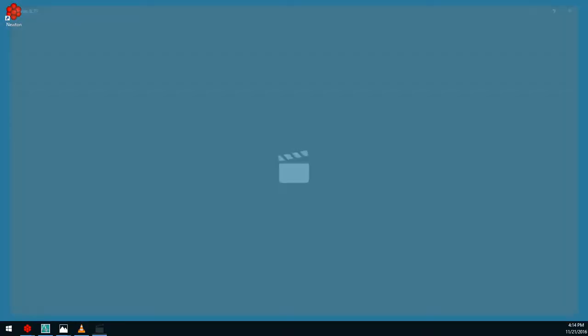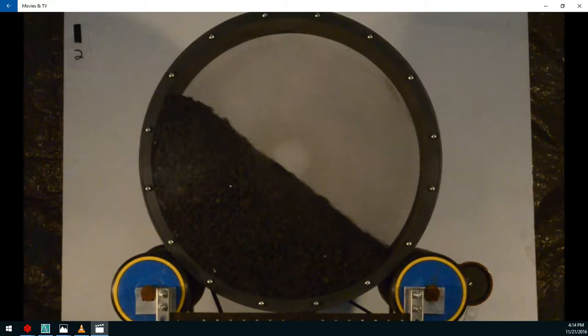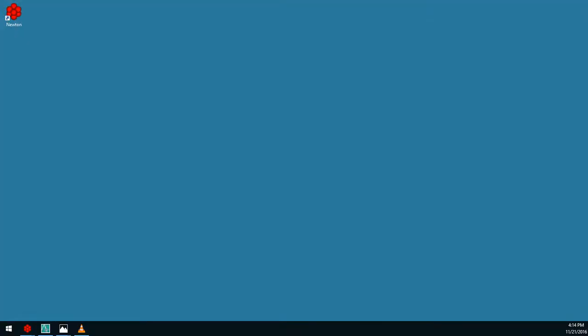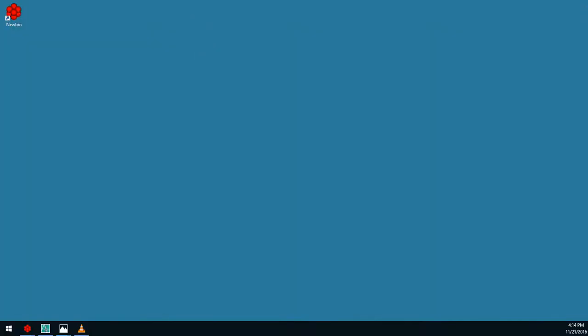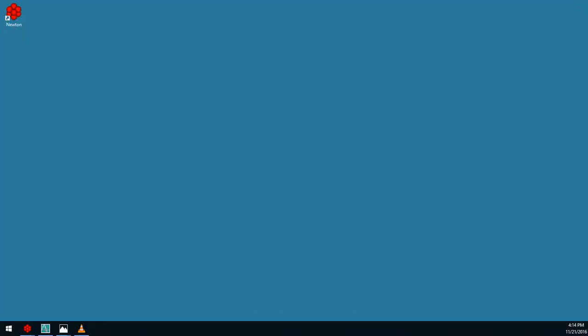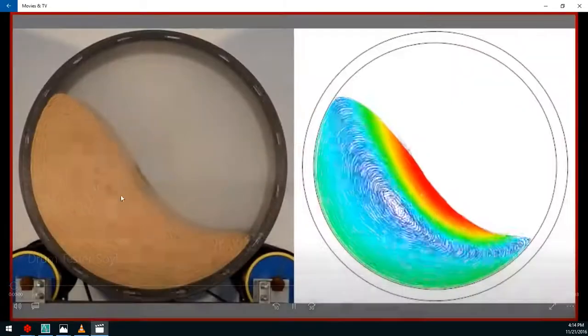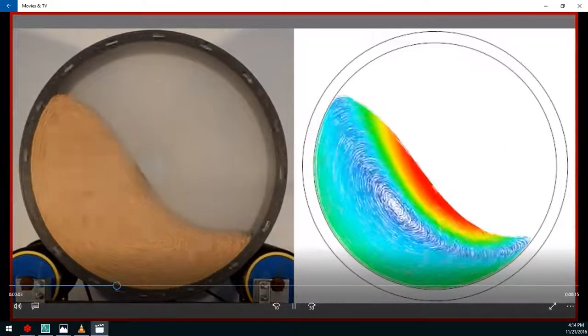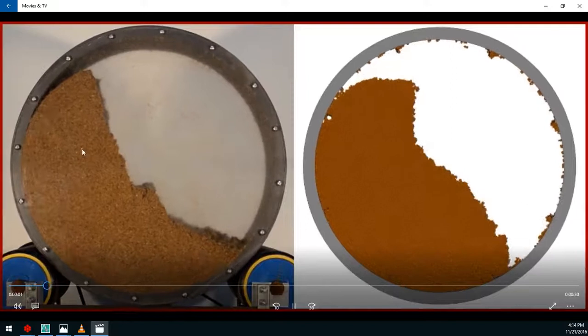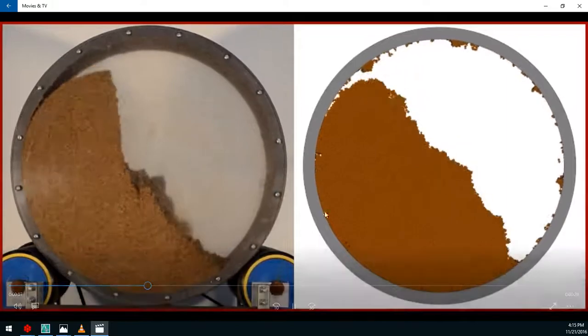But there's also a range of drum testing. We found this test, and there's a range of different material tests that we do, but this one is actually quite nice too, because this gives you some steady state results for a dynamic test. That happens to be coal. This is an animal feed product that you can see has got some interesting behavior. Wood chips, iron ore. And again, taking that and putting that back into the simulation and getting the simulation to match. Here's our wet playground sand again, sloughing off, and the simulation matching that up, which is really quite nice and quite powerful.